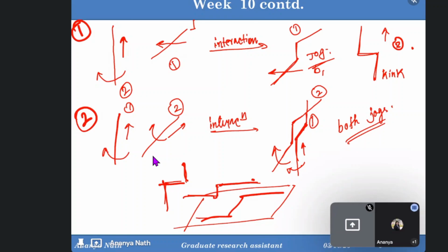See, there are a few conflicting aspects, because when a dislocation is changing its plane, you cannot say that there is an interaction and the interaction is hampering the motion of the dislocation. We agree to that. But when it's changing the plane, you don't know what is present in the next plane. You are concerned about one dislocation present in plane 1, and now the second part of the dislocation is moving in plane 2.